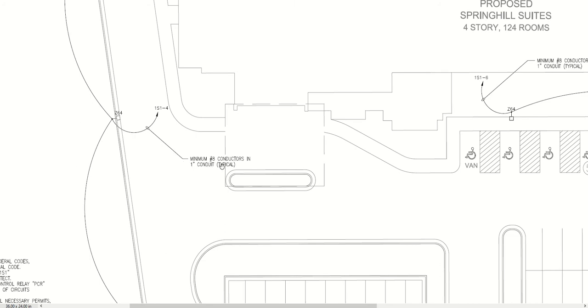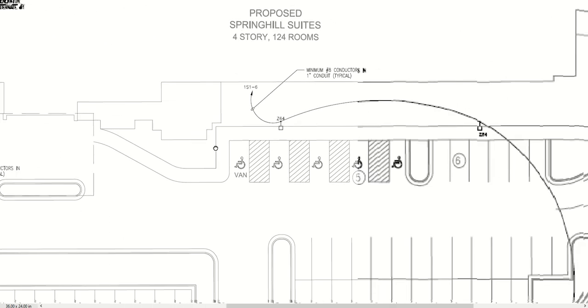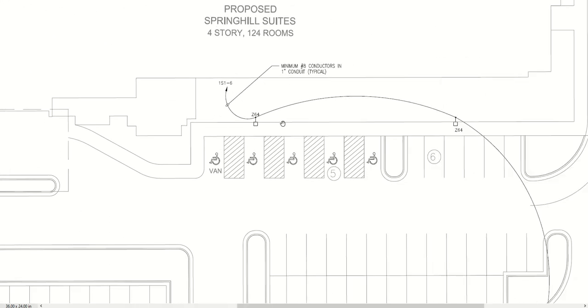And so again, in the conduit section, we hopefully by now would realize that's probably going to require a larger conduit. So we specify here a number 1. So we say in the specs and the notes that everything should be a minimum number 12 with like 1/2 inch or 3/4 inch conduit. But if we know it's going to be larger, we need to go ahead and call that out, and we can do that with the leader line here.